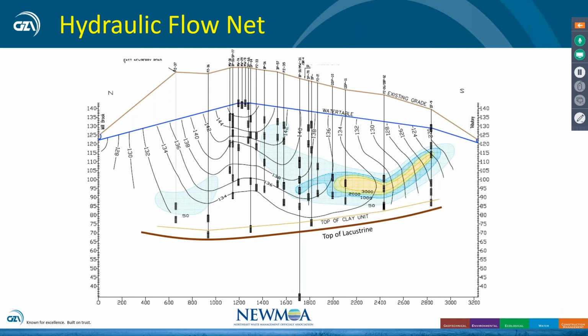But when you look at our presumptive remedies, we have to know in terms of our assessment and our feasibilities where we're going to be looking. So in this particular case, we're located on top of a hydraulic divide. So why not put our contamination sources right on top of the divide? An excellent location to put things. Things sink very rapidly. This is probably one of the highest vertical flows that I've been able to measure. It's a 1/2 foot per foot. So very steep groundwater flows. That also gets into how we're going to solve the remedy and why some of the geochemistry changes. And we also have a discharge. So we have a vertical upward flow, not quite as fast.